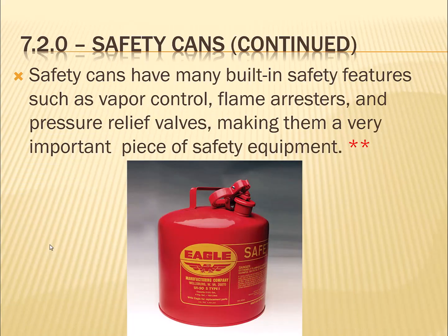So, the safety can, that lid has many built-in safety features, such as vapor control. Well, that's the spring-loaded lid there with a handle on it. Flame arrestor, well, that's the lid. And a pressure relief valve, well, that's that spring-loaded lid. So it's all about the same thing. But the idea is that if there's too much pressure, it'll bleed off. But otherwise, it's keeping the vapor from evaporating off quickly.